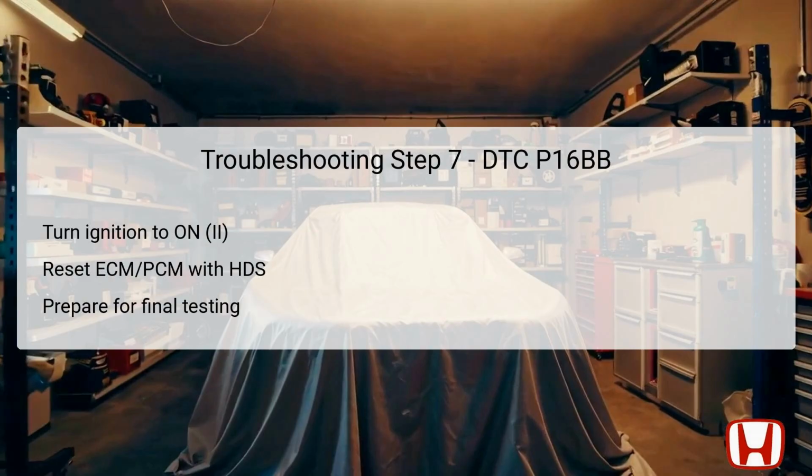Turn the ignition switch to the ON position to pave the way for another troubleshooting phase. Utilize the Honda Diagnostic System, HDS, once again to reset the ECM/PCM settings, which restores factory settings post-repair or inspection.